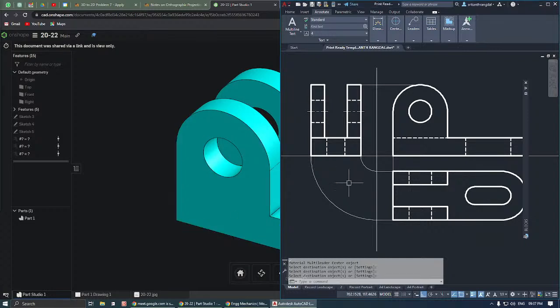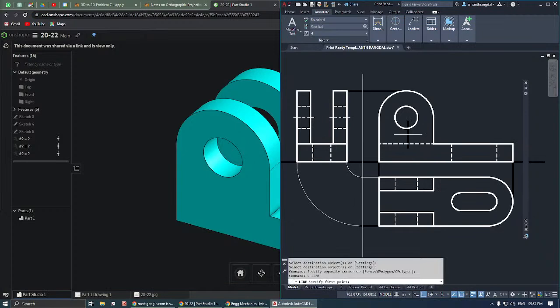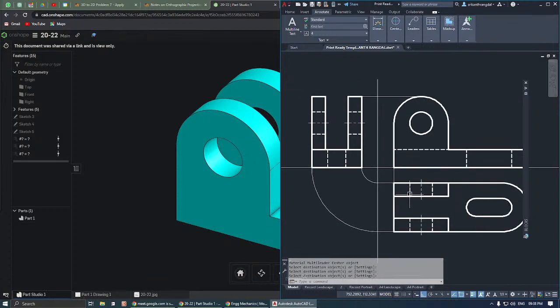Yes, ma'am. So finally we need these axis lines over here. Let's go ahead and take axis lines here. You can just click on these points, scale it a little. Scale command you can use to expand it a little. 1.5 or 2 you can use, and then record. So these are the axis lines which you need to place, and that should do. I hope this problem is clear.